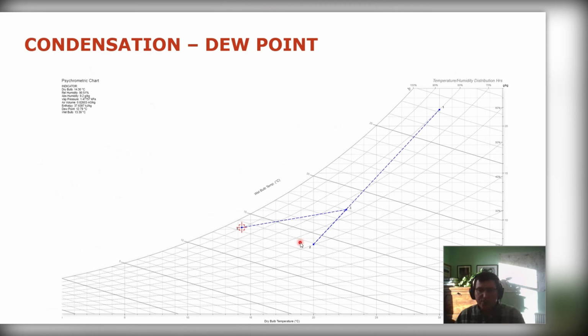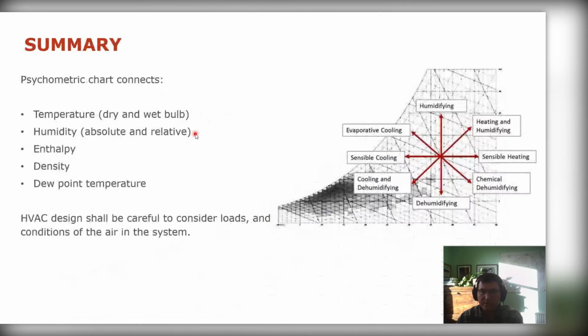And that's where you start getting problems with mold and condensation, because in sizing, people correctly address the overall cooling requirement in terms of the sensible heat, but they didn't think about the moisture removal. They've not accounted for it properly. What they should have done is cool it further and then reheat slightly, and that would have provided a better condition. That would be actually taking away the moisture as well as taking away the heat from the space, and that would be more of a correct way to do it.